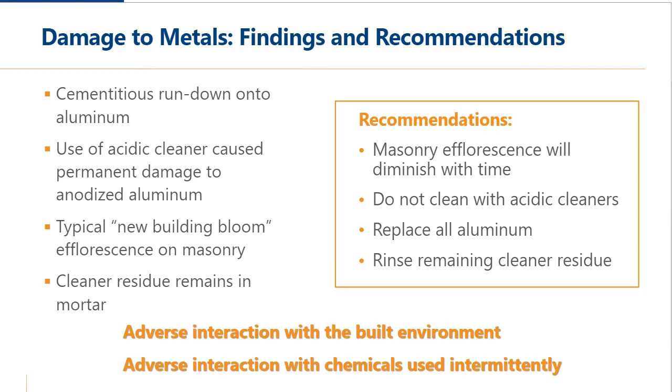So what did we tell our client? We said that masonry efflorescence will diminish with time, and it's cleanable, but it's also just sort of expected. They got to be very careful with acidic cleaners, which will remove the efflorescence, but if they're not thoroughly protecting susceptible materials, they're going to have the same problem. The aluminum cannot function as intended, and it's still a brand new building under construction.